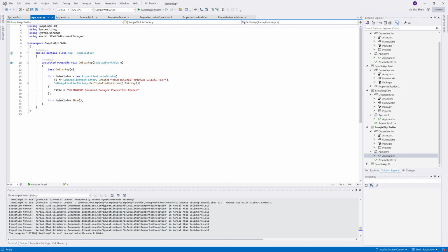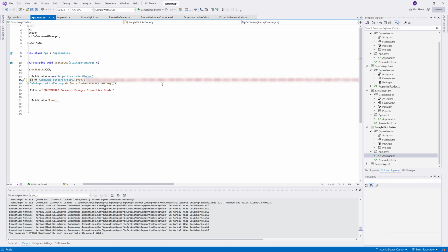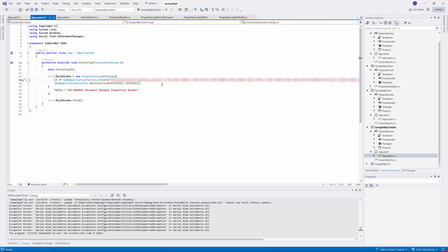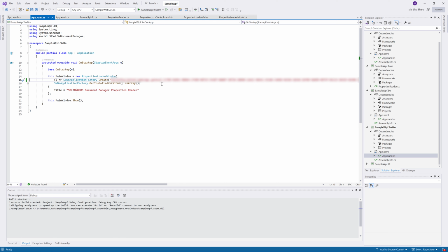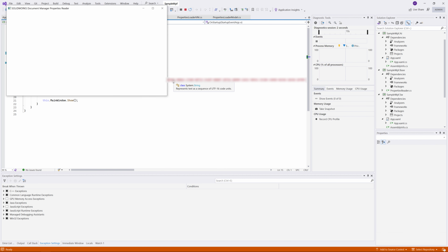The API itself is very different structure to SOLIDWORKS API. So if you have ever written anything in SOLIDWORKS Document Manager, you will see that it has very different classes. So code from SOLIDWORKS will not be compatible with the code for SOLIDWORKS Document Manager. However, in xCAD, we will use the same code to read the properties from the SOLIDWORKS files using Document Manager. You need to request your own SOLIDWORKS Document Manager key in order to use SOLIDWORKS Document Manager API.